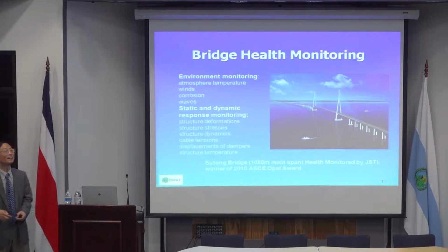And typical sensors are either GPS-based or strain-based. Strain-based is typically optical, like fiber-optic based. With load tests, structure testing here in the laboratory, we know all kinds of different sensors and instruments. So, for example, people may say, okay, for that cable-stayed bridge, let's put some sensors on these cable stays.